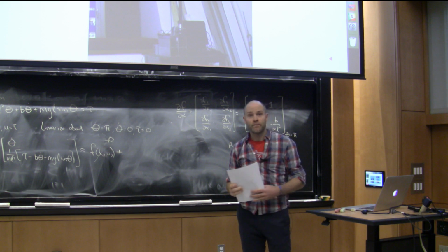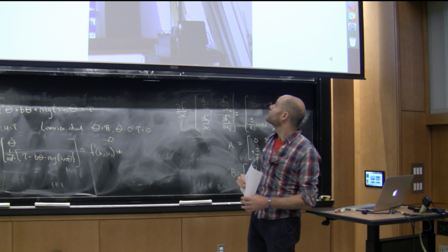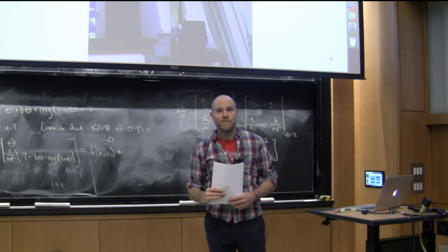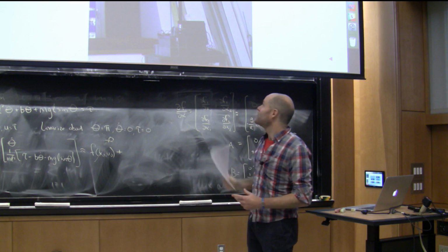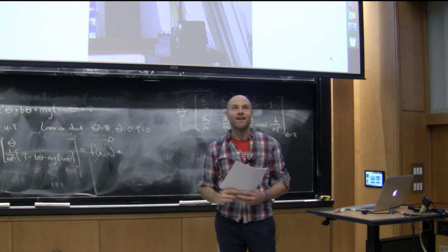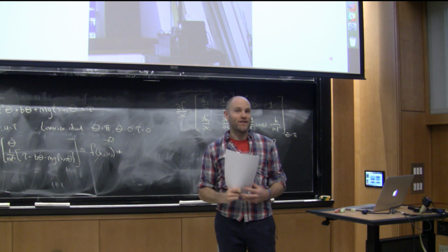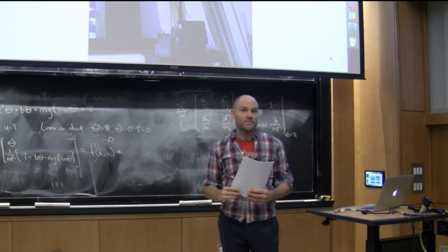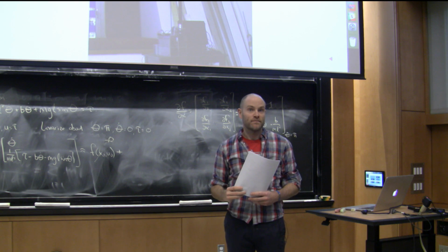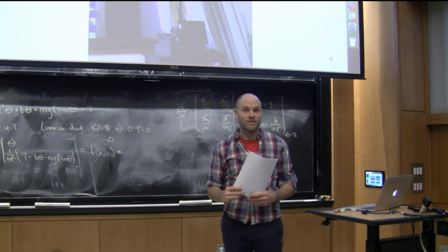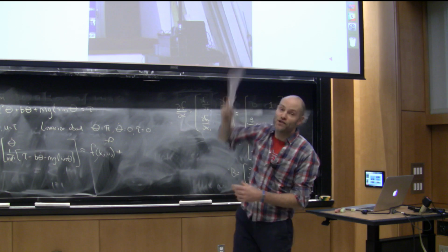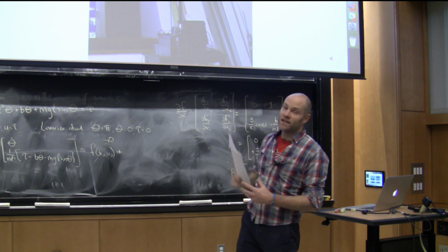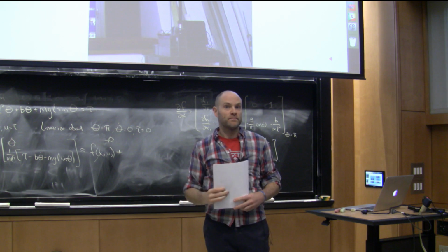Yeah? And for this problem, are you linearizing the system around this final pose or around the trajectory starting from the initial state? This is at the final pose, but the way we get there is by linearizing along a trajectory and stabilizing the trajectory. So if we linearize around the final pose, we can start somewhere around that pose, not everywhere. Correct. So the swing up part, I haven't told you how to do yet, but you're on to me. But at the top, it's just vanilla LQR.